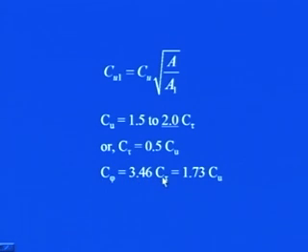All these things we have already discussed in the last class. So, if this C tau is half of Cu, you substitute this particular expression here in this expression, that will result into 1.73 times Cu. So, using these three relations, that is this one and this one, we can get the value of Cu for the foundation from the value of Cu which we have found out for the test plate. And then once we know this Cu1, that is Cu for the foundation, using this expression we can get corresponding C tau, and then using this particular expression we can get corresponding C phi.